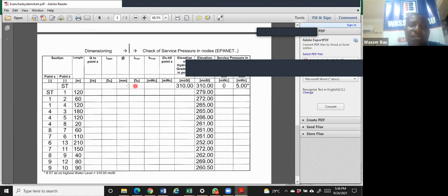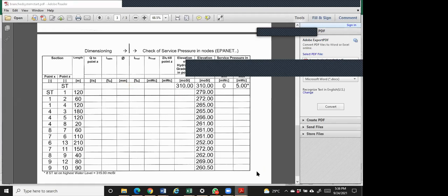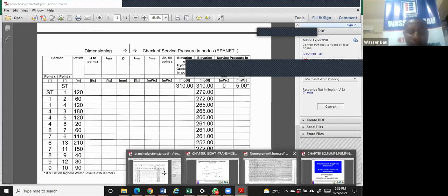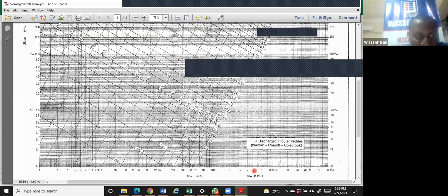The real slope is that after making an assumption of slope, I can go back and calculate the real slope. For instance, I got something on 2.8 against 5%, and it was giving me somewhere in between here. So when I chose this, I'm supposed to go back, get the new Q and then get the real slope. That one is basically for academics.